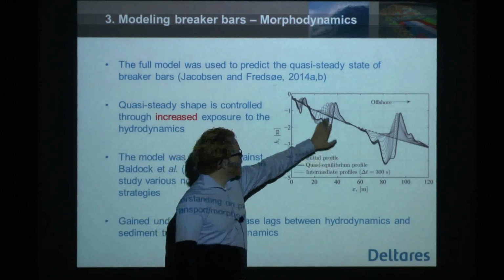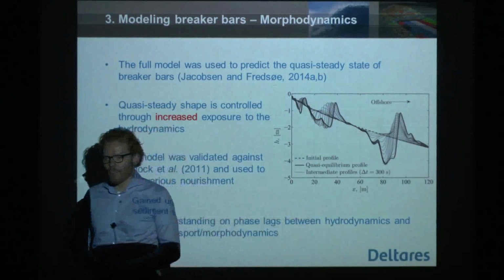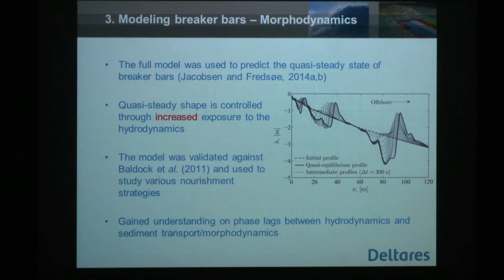And then later on, a second breaker bar starts forming, and a third breaker bar once you have breaking and reforming and re-breaking of the waves in the surf zone. And what we have always also gotten out is a better understanding about phase lags between hydrodynamics and sediment transport, and what elements in sediment transport we need to include, and at what level of detail, to get the correct magnitude and direction of the transport.